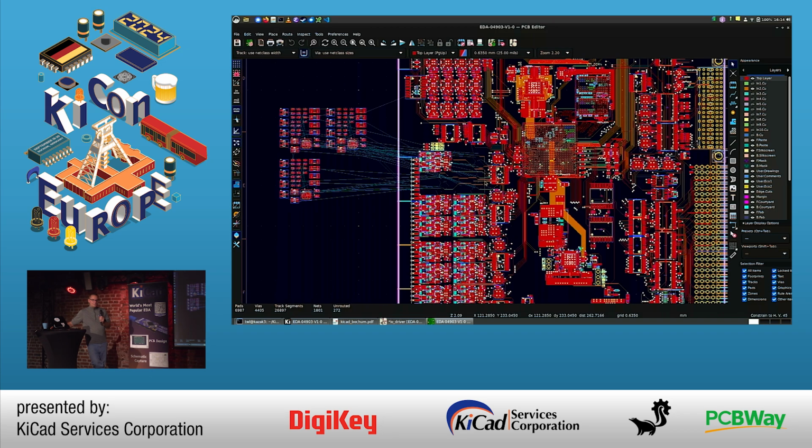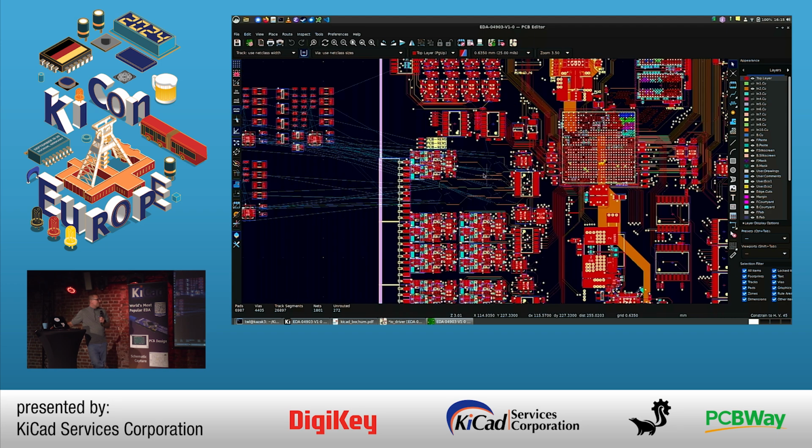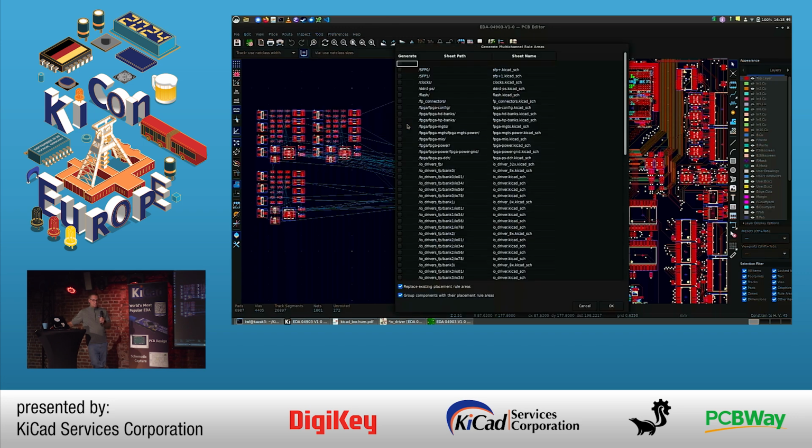So I deliberately broke it because this PCB has been fully routed already. Let's say this will be our reference channel, and we would like to arrange these components and route them automatically to make 3 other channels. So what do we do? Tools, multichannel, generate placement rule areas.